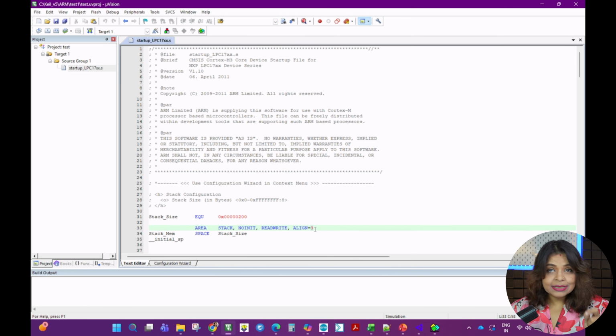As soon as the ADC performs its task, it generates an ADC interrupt, which interrupts the normal flow of the processor, and the processor understands that there is an ADC interrupt. How will the processor know where to go? For the ADC interrupt, I define the interrupt handler, where I say this is digital data generated and I want to read it and do further processing, display it, or use it for a delay in some application. It is based on the requirement of my embedded system.